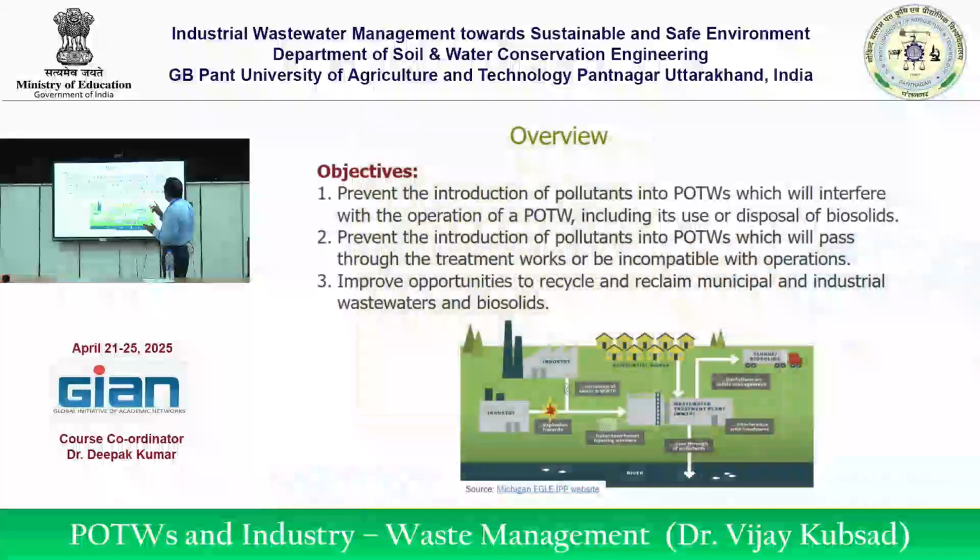So what are the objectives? Prevent the introduction of pollutants into the POTW, that is the wastewater treatment plant, which will interfere with the operation of the treatment plant, including the use or disposal of biosolids. Prevent the introduction of pollutants into the POTW which will pass through the treatment works or be incompatible with its operation, right? And improve opportunities to recycle and reclaim municipal and industrial wastewater and biosolids.